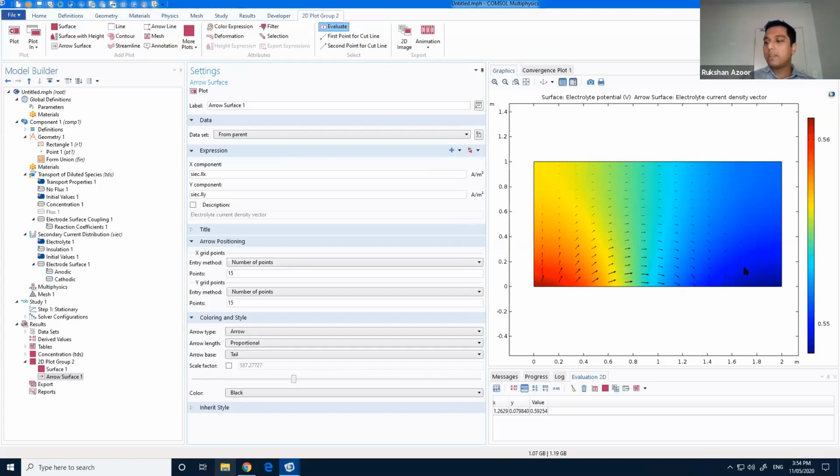So just a quick bit of background information on what we are seeing here. What we simulate here is something called differential aeration. If we have a soil domain partly covered, oxygen can come through only one side. This part will be depleted of oxygen, and when there's a depletion of oxygen, the corrosion rate in that region can increase. That's called differential aeration corrosion.